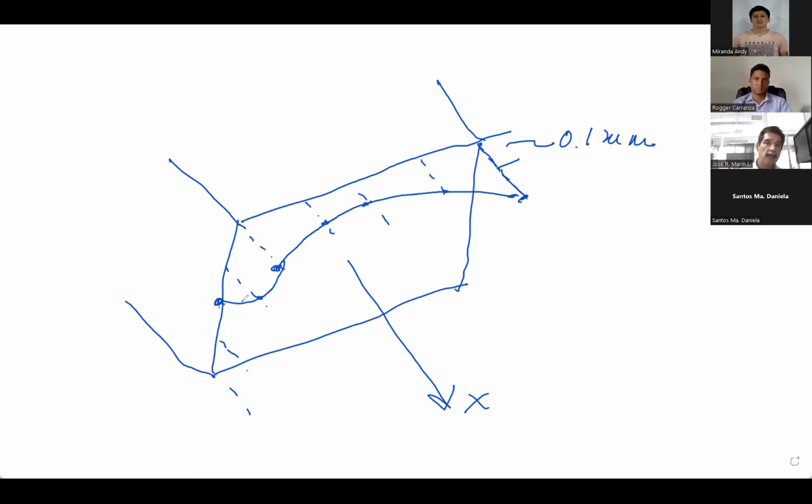Okay, and then downwards, something similar, right? Maybe it's possible that this is negative. So the idea is that if this would follow the kinematic assumption, this would be a straight line, right? So it would be something like this. And here, you will have a single value for the whole deck. That's following the kinematic hypothesis. The section is like this, and it does this and rotates, but it's still straight.